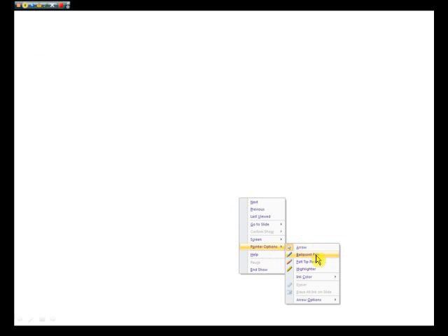Okay, nice clean slide ready to go. So what we need to do now, we're going to be calculating quite a bit of maths. So let's just refresh our memory as to ZS. ZS is equal to R plus 1 over j omega C, and ZP in its nice simple form is R over j omega CR plus 1.